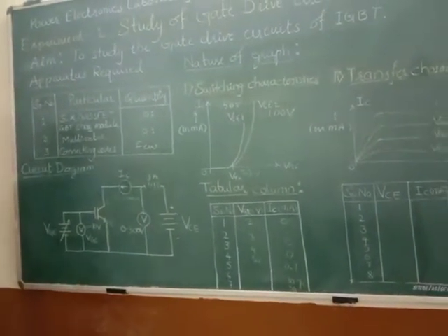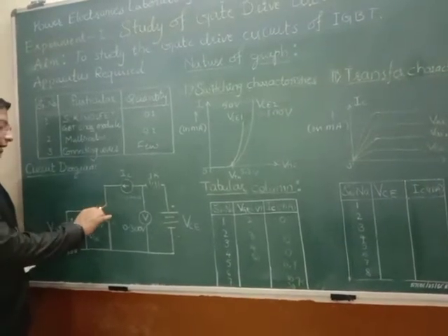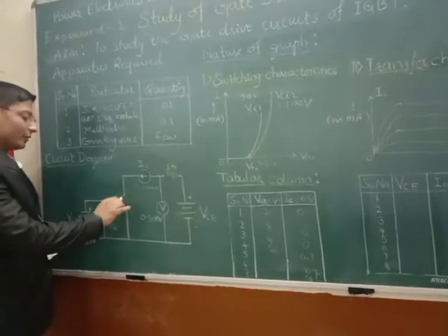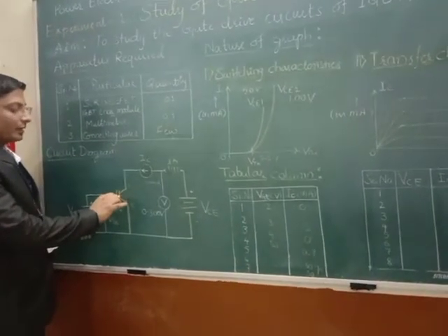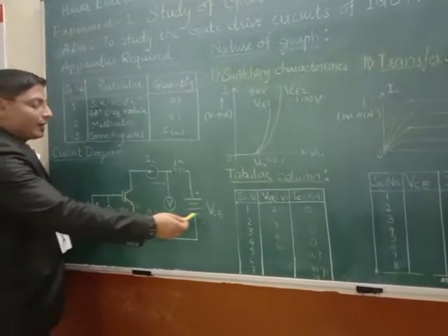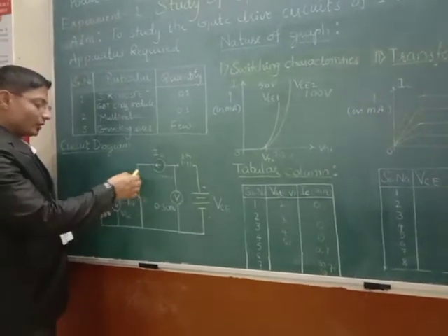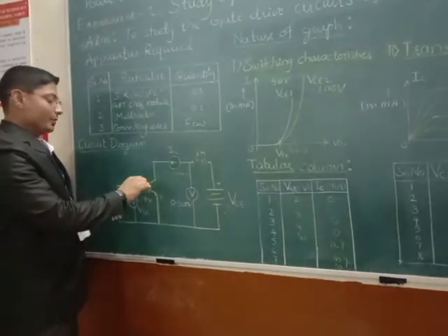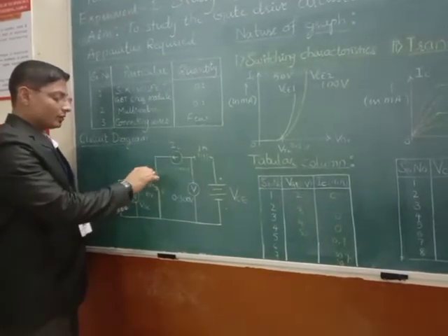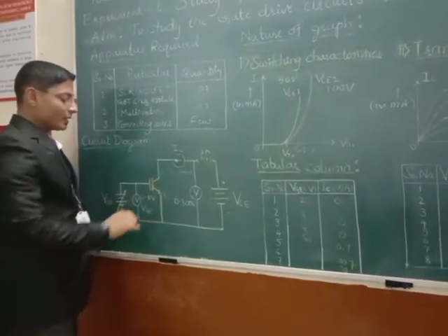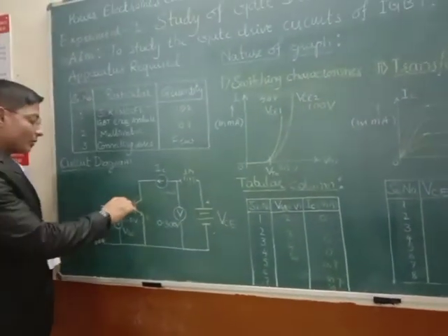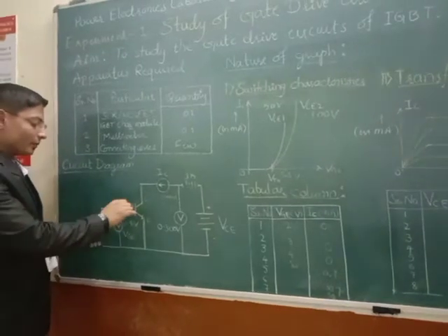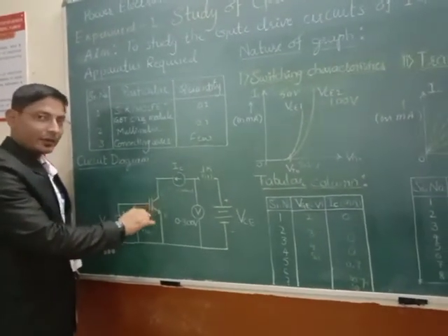What is going to happen is that there will be electrons available between collector and emitter, a layer of electrons formed here, but limited electrons will be there. When VCE is increased, current will start flowing, as that VGE is sufficient to turn on the IGBT. But how much current will flow? It will depend upon what amount of electrons are available. How will the number of electrons be decided? It will depend upon what amount of pressure is applied at the gate terminal.